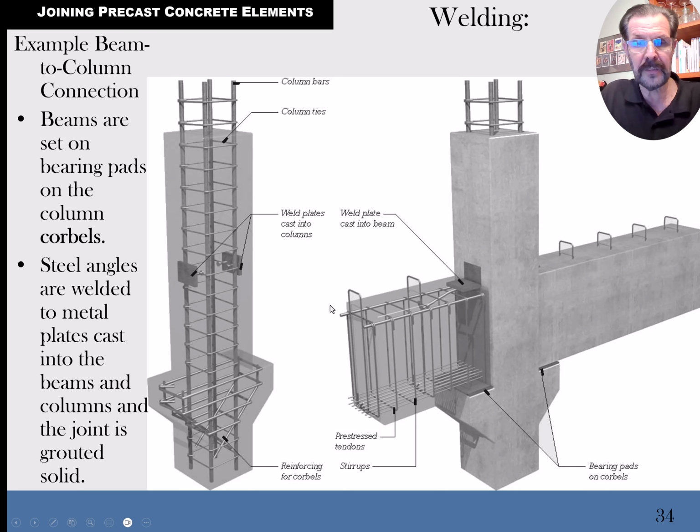Most of the time, we electrically connect all of these metal plates with rebar that's all welded together in a way where you can count on it to be electrically connected. That way, the welding ground wire can be connected in one place, and you can go across and weld this stuff without having to keep moving your grounding cable. So that's just another side note here. But anyways, you can see the rebar poking up out of the beam and sticking out over here too. And all that gives you a positive connection.